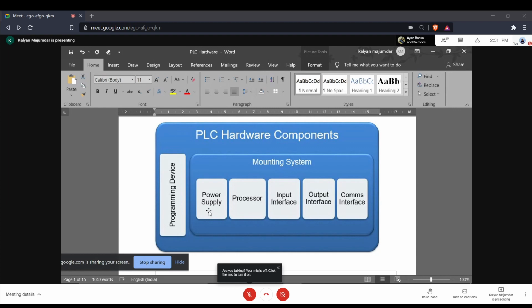You also require a communication interface, for example, if you want to connect a display. A display is not an integral part of a PLC, unlike, say, a laptop. Your laptop always comes with a display, but a PLC does not come with a display as an integral part. Of course, you can order a separate display for showing a visualization, more commonly referred to as an HMI. But then that display hardware will have to be connected to your PLC hardware.